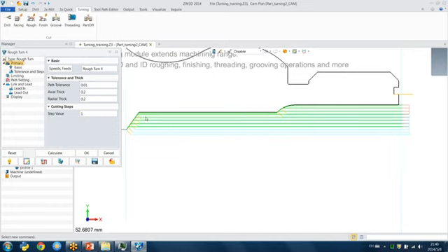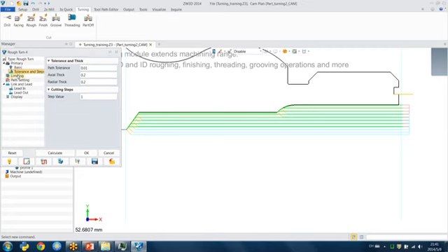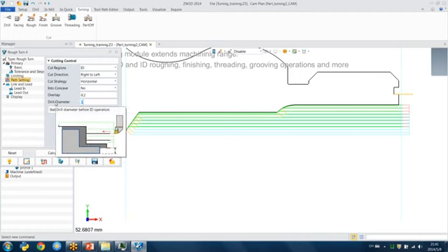But you find in this hole, I already drilled the hole. Actually, in this toolpath, I don't need this toolpath, so I need to tell this operation I already drilled the hole. Okay, the diameter is 10.